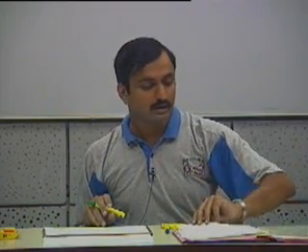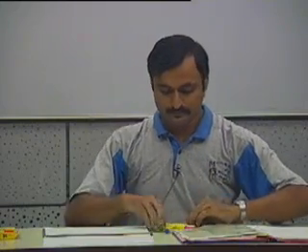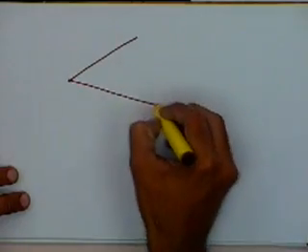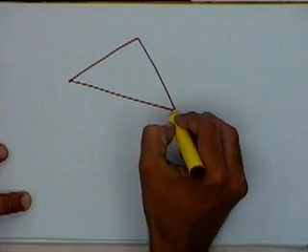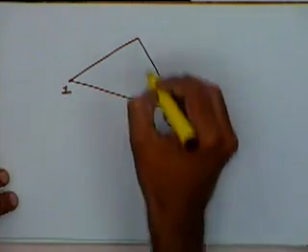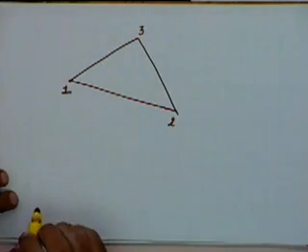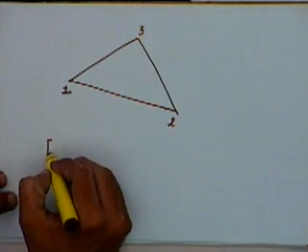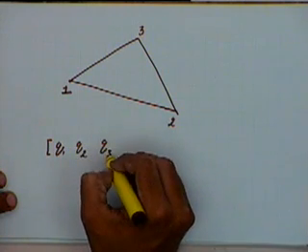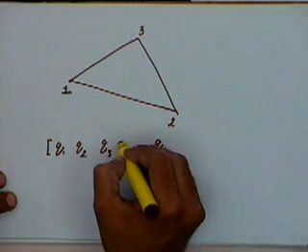If we quickly look at how to use Galerkin's approach for the same element, that means if we have a triangular element like this, and we have said that its displacement matrix is given by q1, q2, q3 till q6.